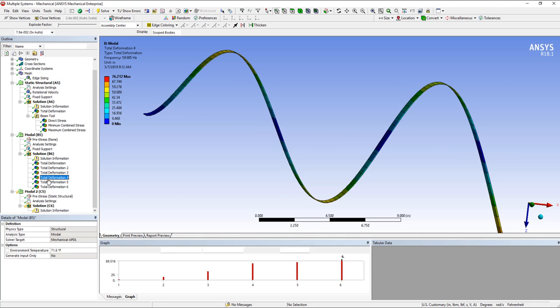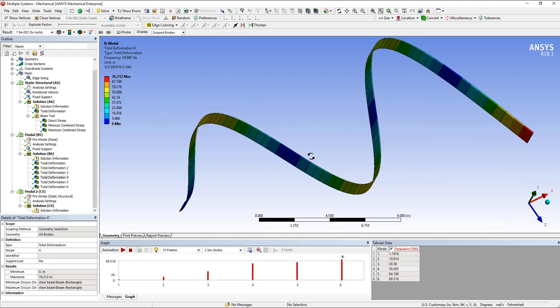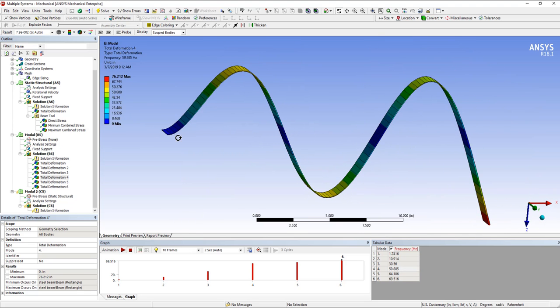Okay, so now let's come back to these modes. It looks smoother, but you can see that the change in frequency was negligible. So I'm well converged in terms of the frequencies, even with the coarser mesh. The graphics just didn't illustrate the curvature that was being calculated effectively. So that's the unstressed value.